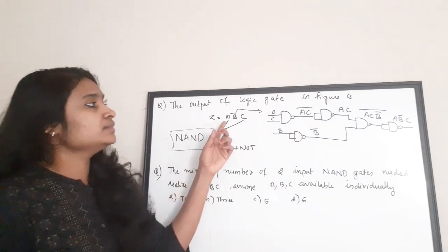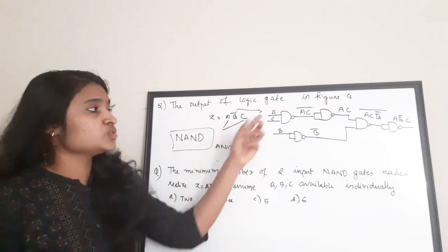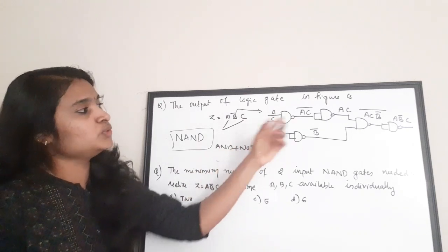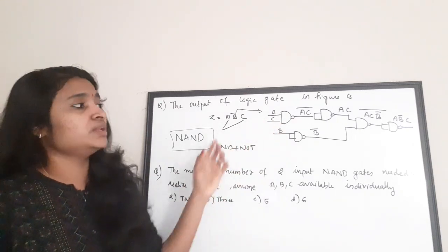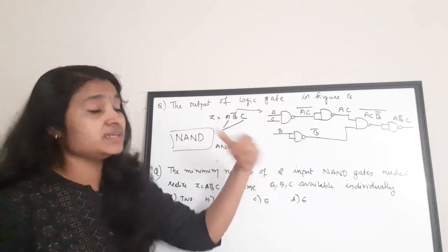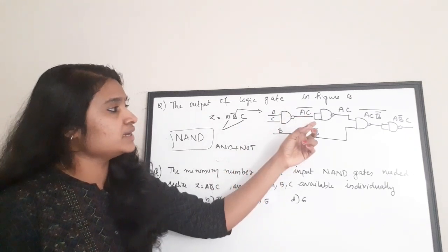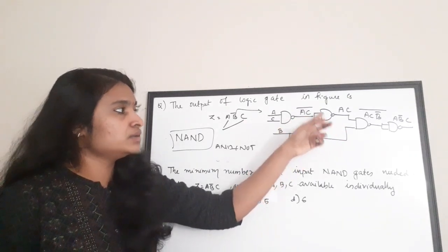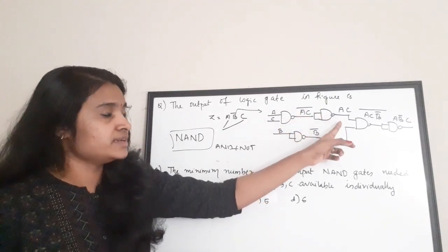We will take the two variables which are in the original form together and the complemented one separately. If you start doing this, you can very easily complete your answer. It is AC, we will get AC bar, we need originally AC. So we'll again take a NAND gate, short its input. You can apply this to the input of this shorted NAND gate, you will get AC.